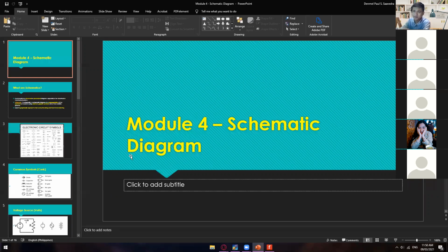That's a rule of thumb: you must know the limitations of your components to avoid burned or failed components. Okay, so polarity and then the limit of the voltage that it can accept.